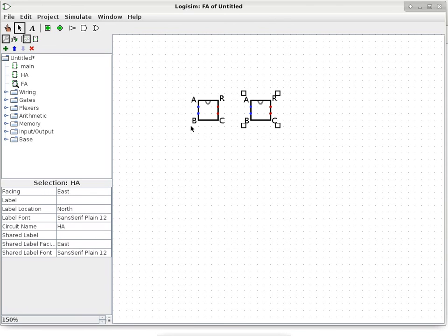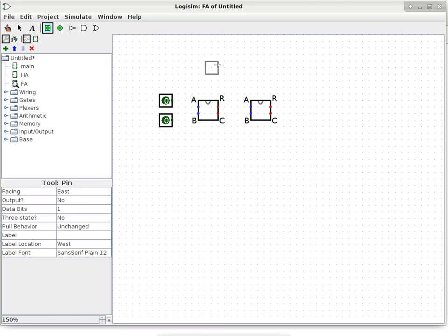All right. Now, with a full adder, we have 2 inputs, right? The 2 bits that we are supposed to add for this column. But we have a third input too. Who's the third input? Carry. The carry from the previous digit. Okay. All right. So we'll go ahead and handle all the input pins first. So here's the input pin of the first number. Here's the input pin of the second number. And here's the input pin corresponding to the carry from the previous digit.